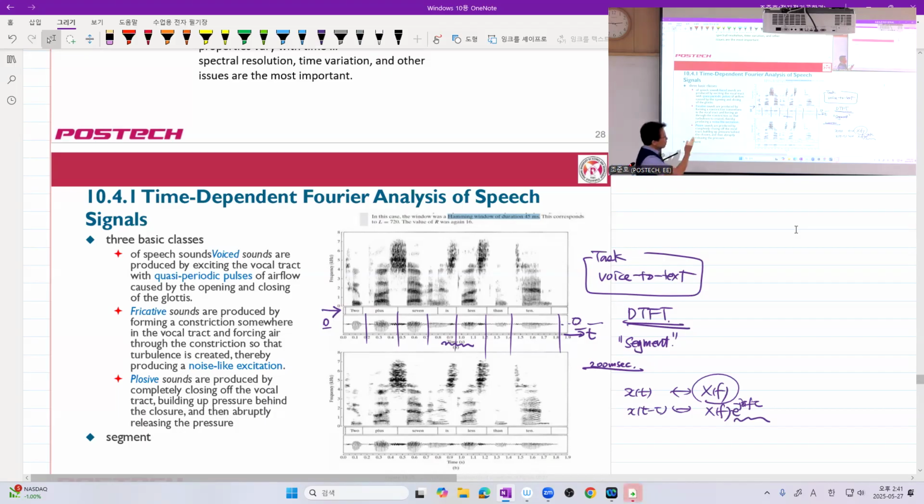but still, this technique is quite often used in digital forensics. For example, when we make up a person's voice or combine them, sometimes what happens is that the background noise level suddenly increases. So by just plotting the short-time spectrogram, you may see that this part and that part are from different noise environments. For example, here, our air conditioner just started to operate again.